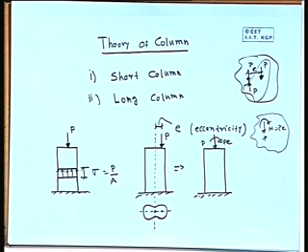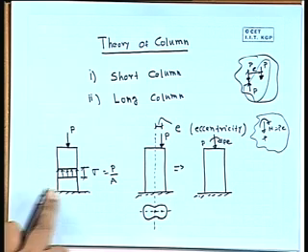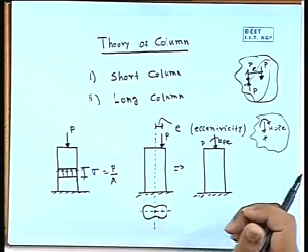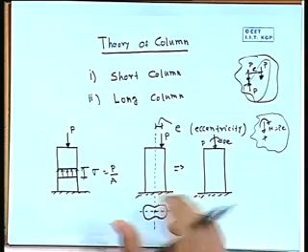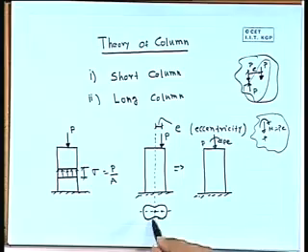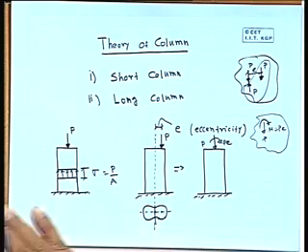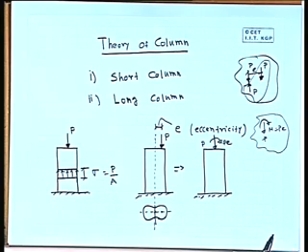Now, the effect of P, you know, P acts at the centroid, there will be a uniform distribution of stress and that will be P by A, and there is a moment that is P into E. So, if we apply a moment here, we know it will generate a bending stress, and bending stress at the neutral level will be 0 and it will vary in a linear manner, right. So, if we take the problem in this manner,